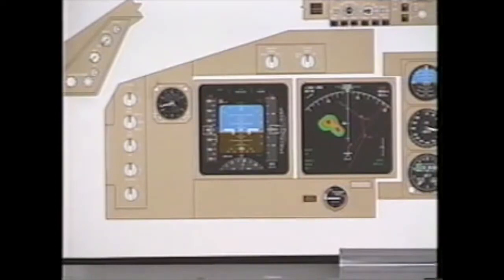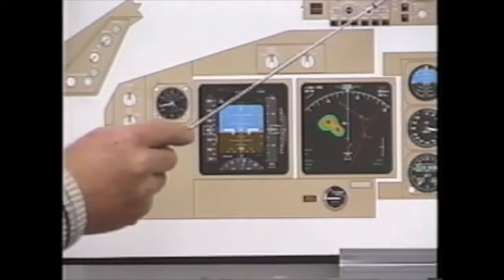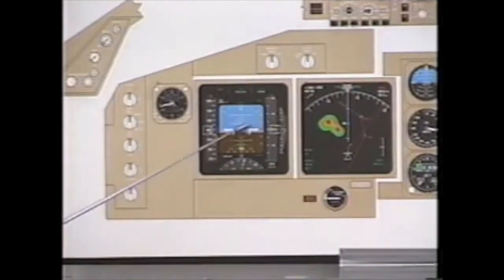3 flight directors, left, center, and right. As a result, with the flight director switch turned on, the flight director displayed is the one selected through this switch, in this case the left. Please remember that a flight control computer can either give you an autopilot or a flight director. It cannot give you both. So if I was to engage the left autopilot after takeoff with the captain on the left flight director, the captain's left flight director will disappear.